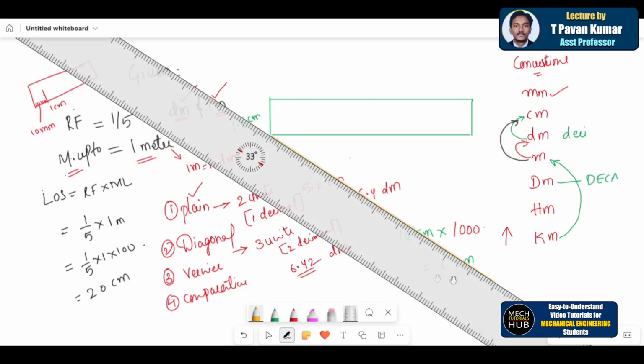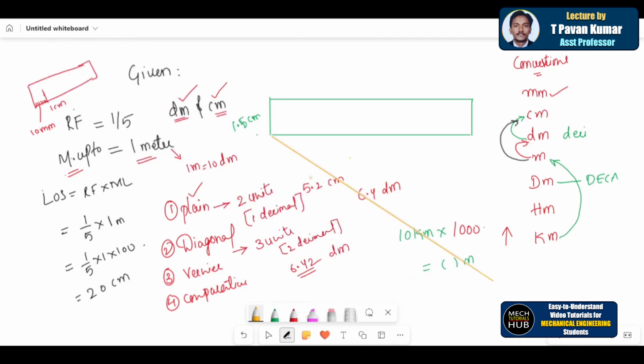I draw the line of infinite distance. Then I'll divide this line with my convenient dimensions. Let me take green color and divide. I need to divide this into 10 parts, maybe 10 mm each. 10, 20, 30, 40, 50, 60, 70. This is the last division.